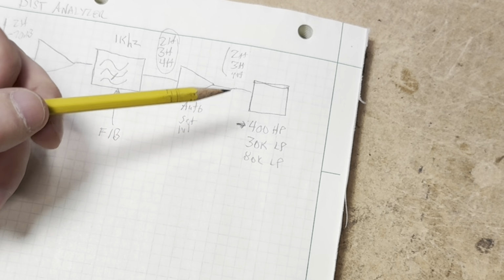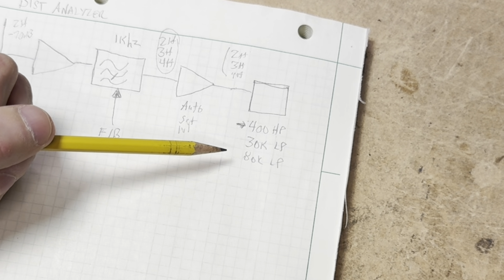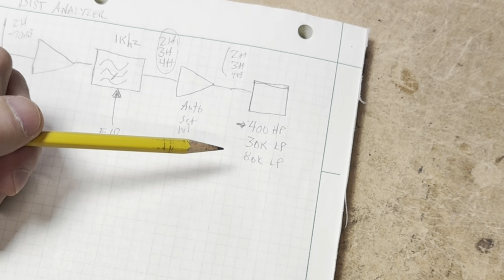Say you're testing an audio amplifier and maybe you have some digital noise at maybe like 100 kilohertz or 120 kilohertz, something like that. You're wanting to test the audio range, which is 20 hertz to 20 kilohertz. Well, 100 kilohertz is certainly not audible, and it's probably not going to be within the frequency range that anyone is going to be using for an audio system.